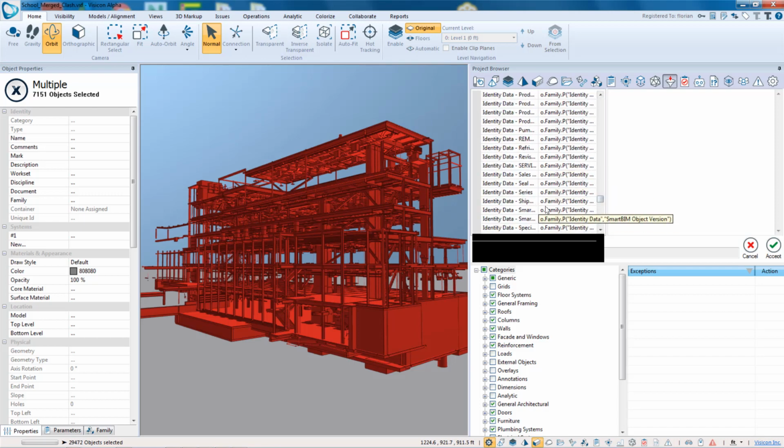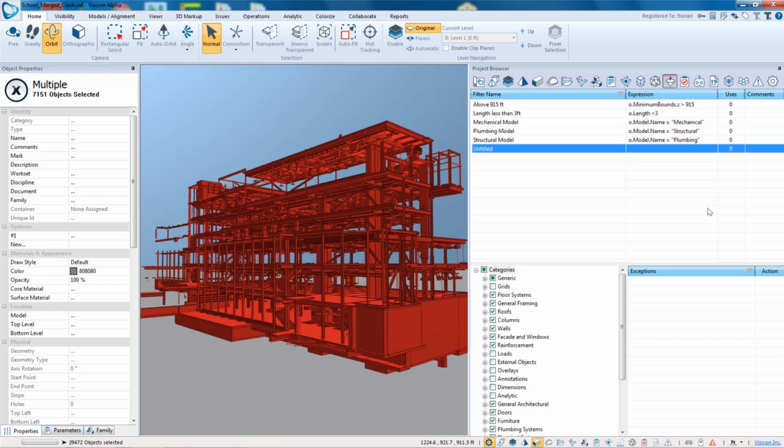So here, for example, I go to mechanical or material, right? So this would be object family parameter. I can search off of materials and finishes, which is the Revit name for a category of materials, and the actual property name is frame material. So I can drill down and write an expression that identifies, and I can do any mathematical or Boolean operation within that expression and use that to identify and extract very specific information in my model. So let's go ahead and cancel out of this. So we have our basic